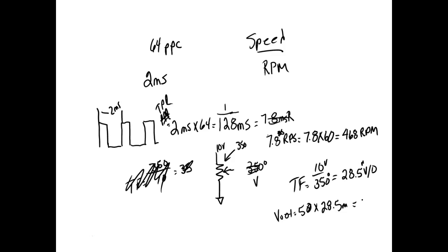Well, PLC is a little easier because you understand what I said. Well, what can I do? Yeah, I can enter in a program, and I can count the number of pulses in a minute, and I can divide that by the number of pulses per revolution, and then multiply that by 60, and I got the time. So you can do one formula.